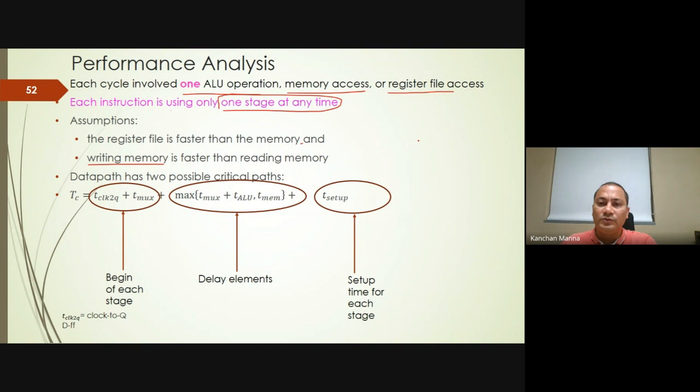For the reading logic, we have multiple stages of multiplexer. If you remember in the lab, we have a 1-bit register, and from that register we are getting the 32-bit data. So we have two levels of multiplexer for reading.